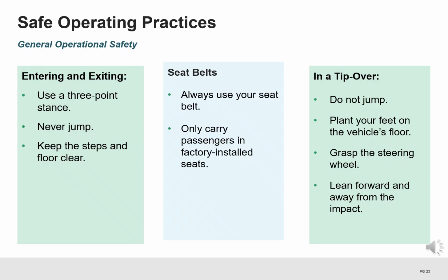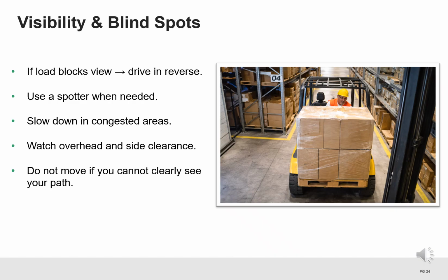Stay in the seat, plant your feet, hold the steering wheel, and lean away from the direction of the tip. Following these practices helps reduce the risk of serious injury. If your load blocks your view, travel in reverse to maintain visibility. Use a spotter when needed, especially in tight or congested areas.